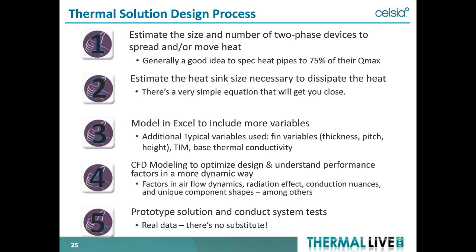Let's walk through the design process for these things. What we normally do is we'll estimate the size and number of two-phase devices to manage the heat, spread or move the heat. We'll generally oversize those by about 25% to take up for any variation in operation, orientation, or power, or any of that kind of stuff. We'll estimate the size of the heat sinks that's required to dissipate the heat.